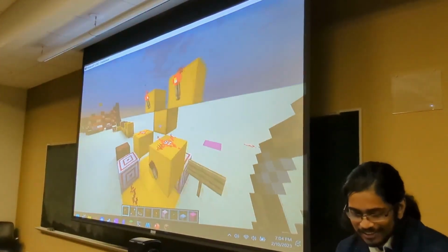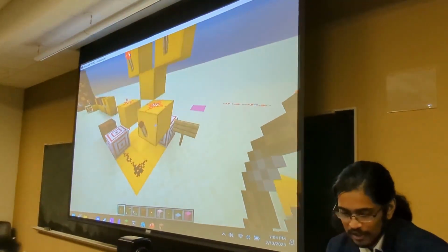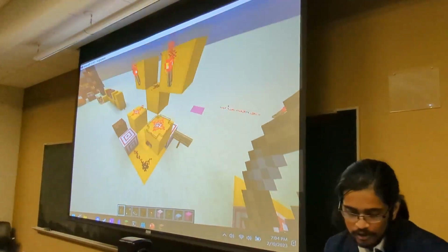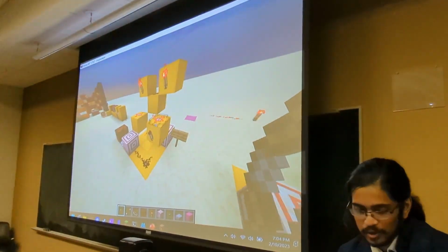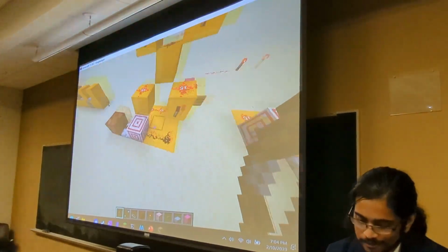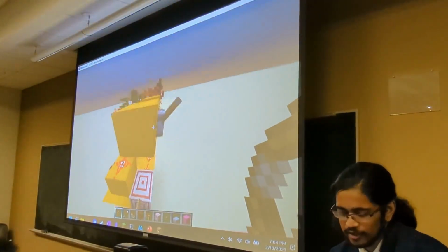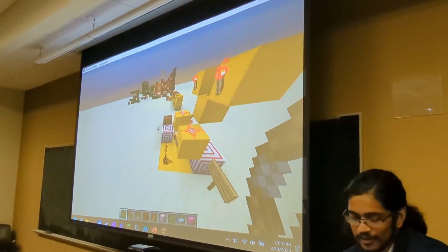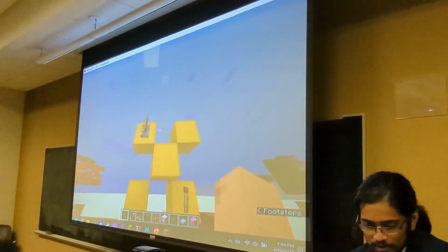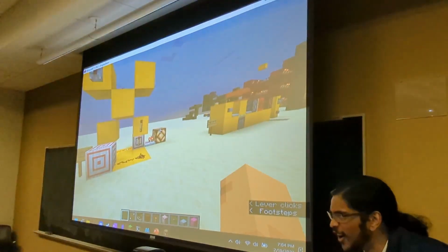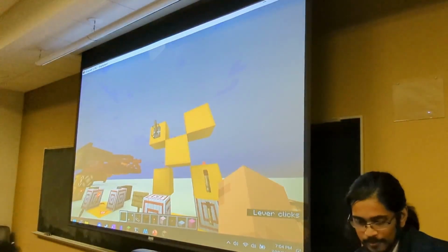It's big and ugly, but basically what you've got is an AND gate here. You have the output here, and then an inverse of your input here, and then the inverse of that going into the reset, right? So if the output is off and you give it an input, then it'll go into the reset. And then you have the inverse over here going into this one, right? If I give this a quick pulse, then it'll go on. If I give this another quick pulse, it'll turn off, right? So we've got a T flip-flop right here.